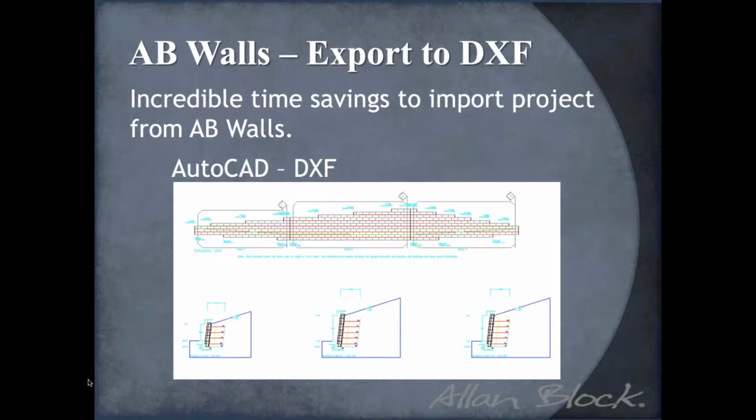So as you design a wall in AB walls, it's one thing to make sure that all of the parts of the wall work. You've got the correct lengths of geogrid, you've got enough buried block, your internal compound stability works out, all of your factors of safety are met. That's all extremely important.